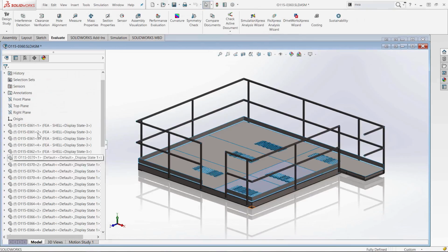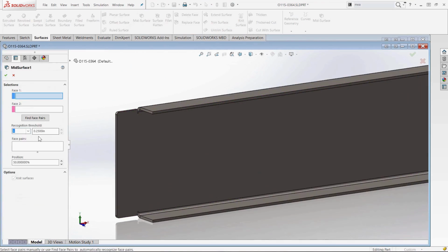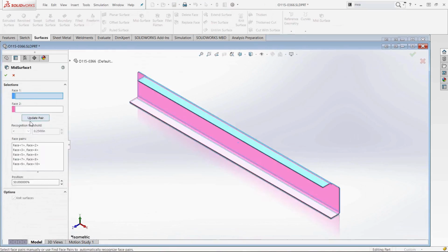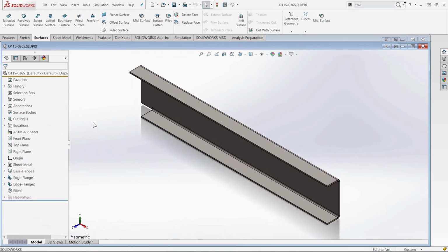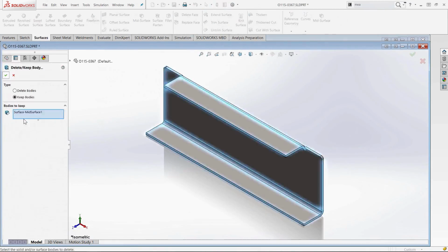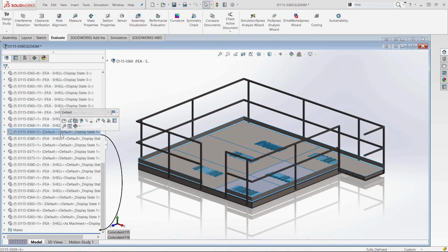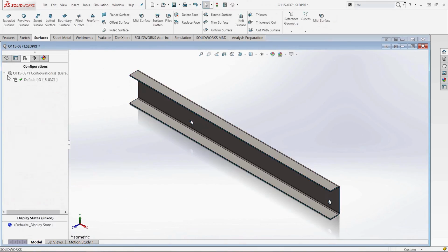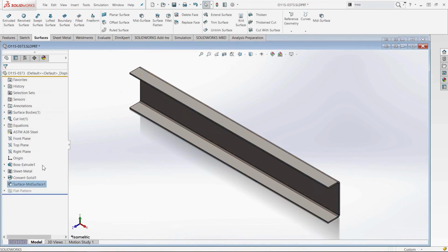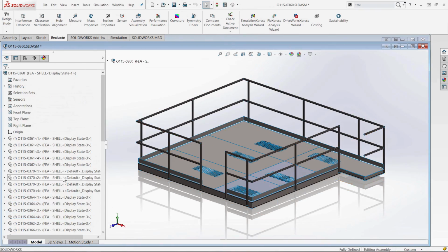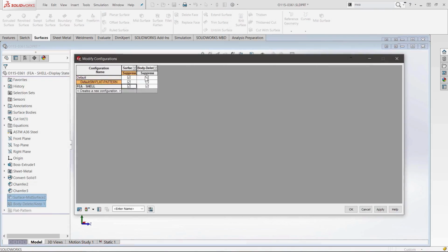So by the time I'm done, my entire feature tree at every level of my assembly should be referencing an FEA shell configuration. What's nice is if you're consistent with this naming scheme, it makes it a ton easier to validate it, as well as there's ways to automate opening an assembly and opening all the reference components to a named configuration.